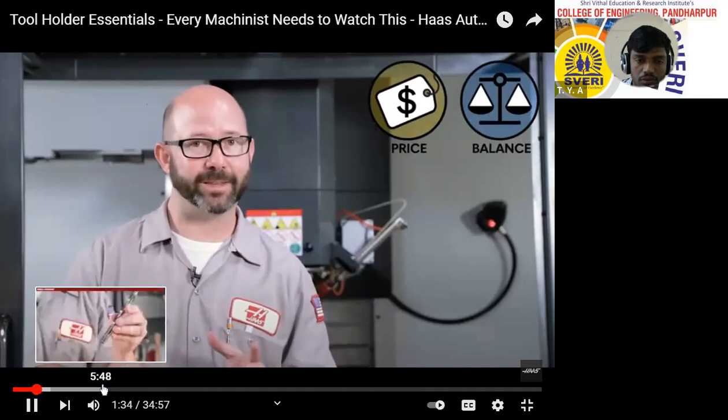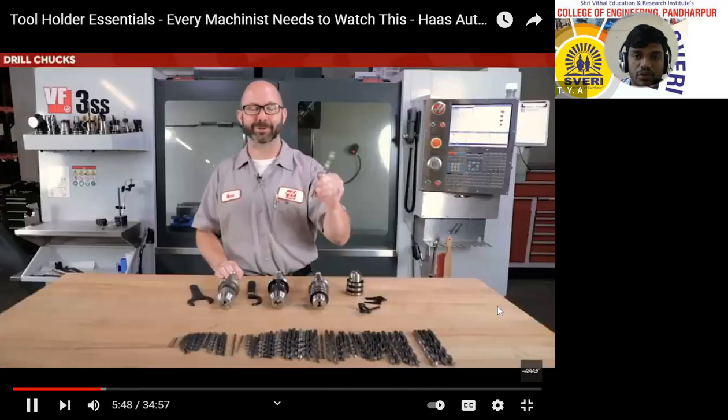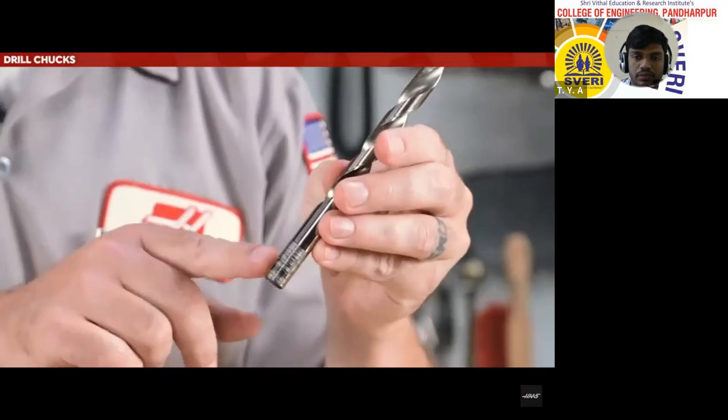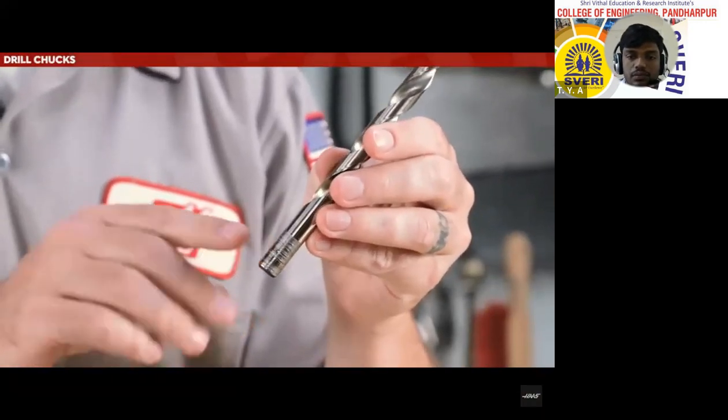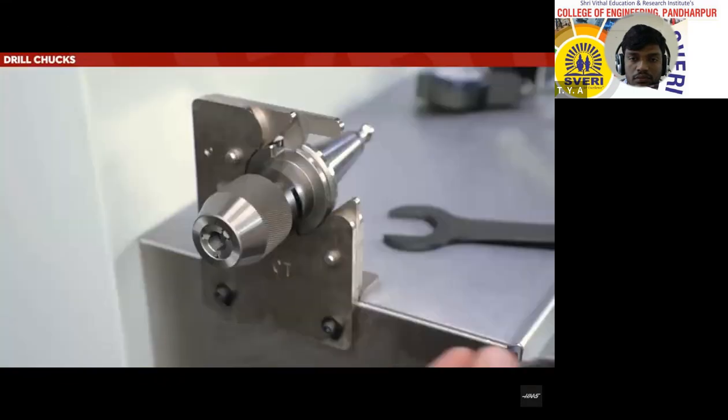Balance. That's just how badly the tool is. This one's pretty cool. This drill looks absolutely horrible. This drill was not tightened well enough and it spun in the chuck, probably operator error. Now, I would not trust this drill for great run out on important jobs, and it probably scratched up the jaws on whatever holder it was used on.